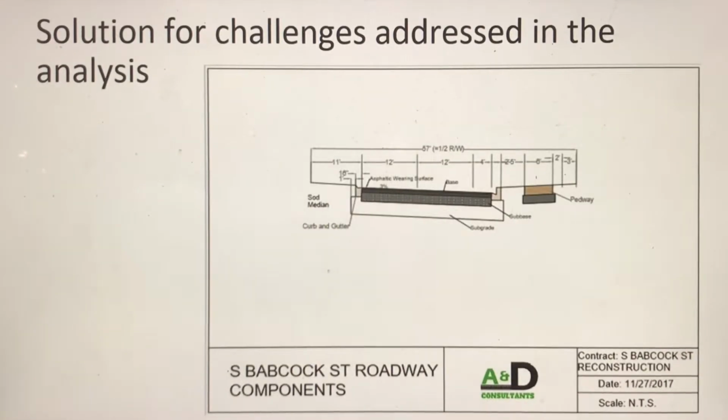We had to take into account the Brevard County typical minimum design standards. The solution to the problem addressed for the roadway segment is to implement a new flexible pavement design. The design approach follows closely the pavement thickness design process for reconstruction in the FDOT Flexible Pavement Design Manual.